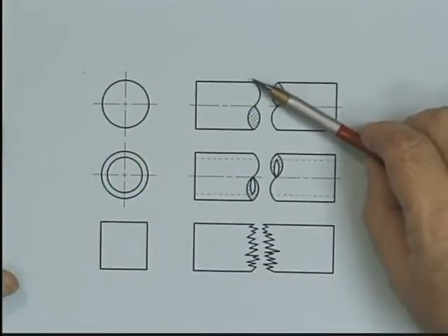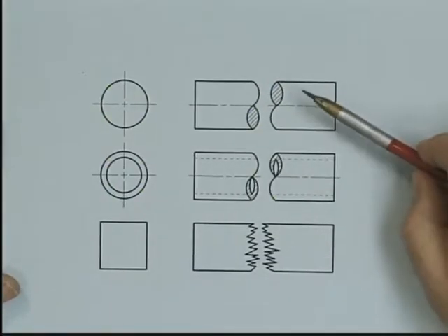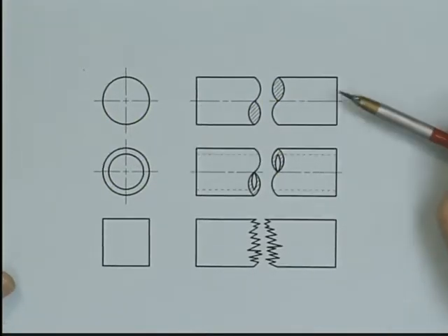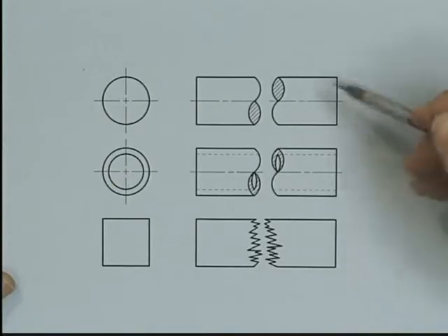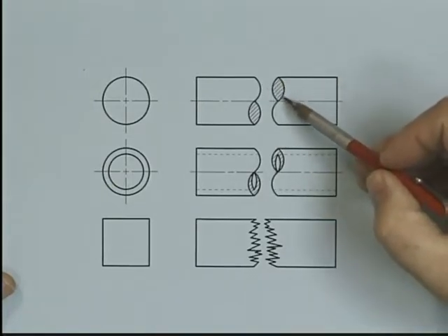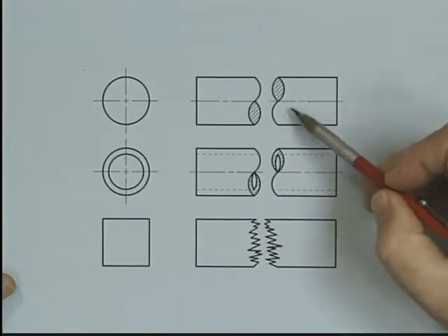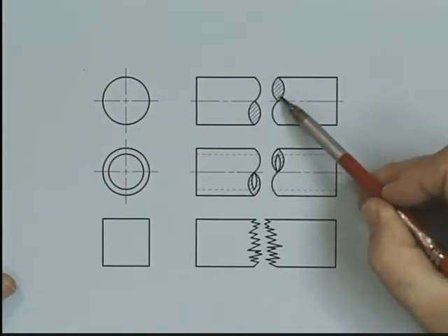And so what we do is we put in what's called a conventional break. There are different sectioning patterns we use to show these conventional breaks. For a solid cylinder, we use this trick. We use this little lazy S and a little, it's almost like an 8 that didn't get finished, and the upper part here is crosshatched on the other side of the break.